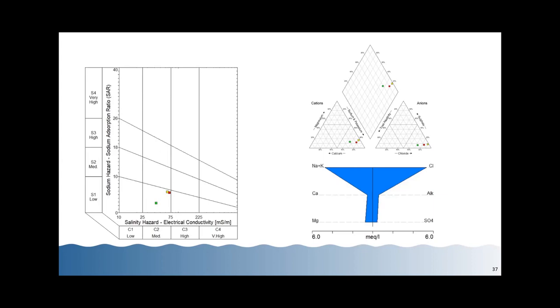The Piper diagram is relative concentrations of the salt ions in the water, and so this can be used to look at waters that are fresher waters versus waters that are from perhaps a saline type aquifer, such as a shale aquifer. We expect to have the shape that we have in the Stiff diagram below, as well as where the 3 points are plotted in the Piper diagram over here, because a lot of our shale deposits in South Africa were under marine conditions, so we have a lot of sodium and chloride in the rocks, and then that leaches into the groundwater.